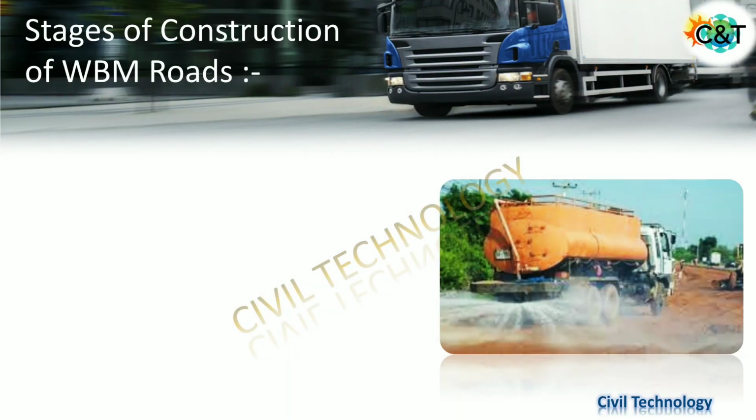Next step is the sprinkling of water and the grouting chemicals. Here you can see this vehicle sprinkling the water on the road surface, and along with that water we mix the chemical, so simultaneously the chemicals are also applied on the road surface.